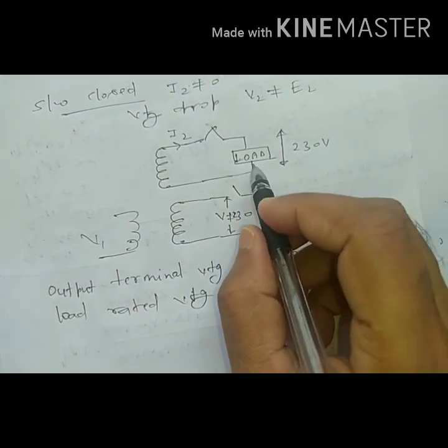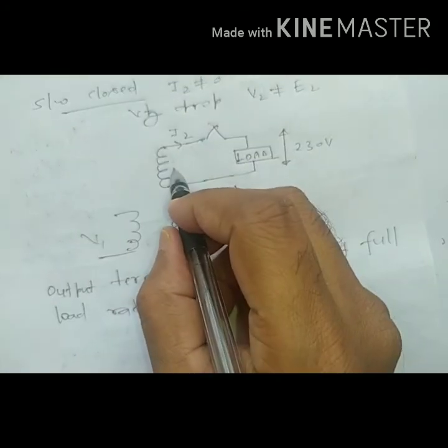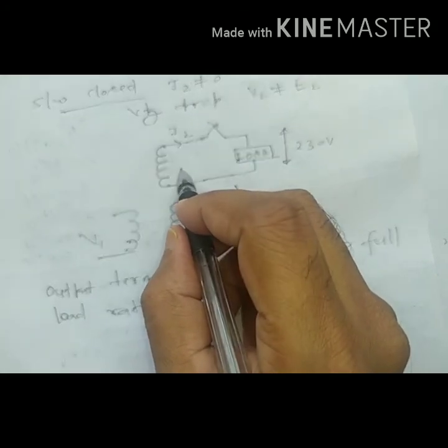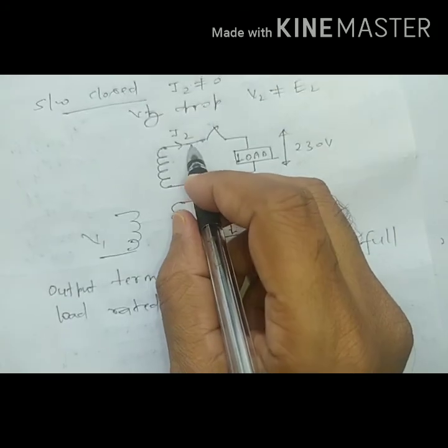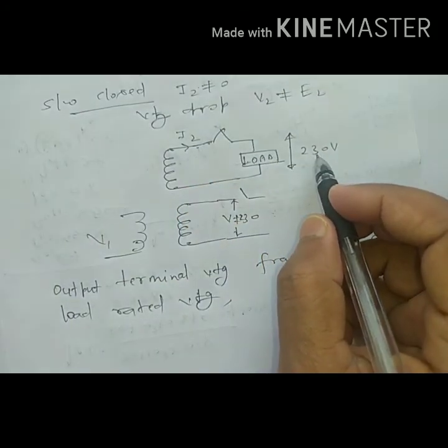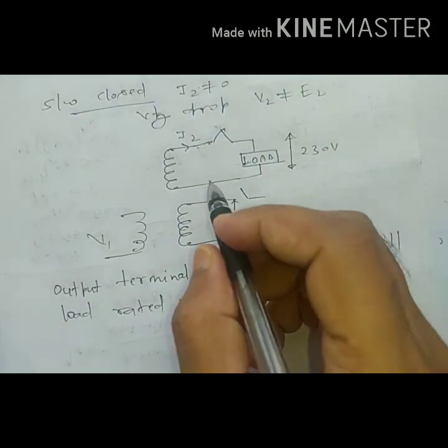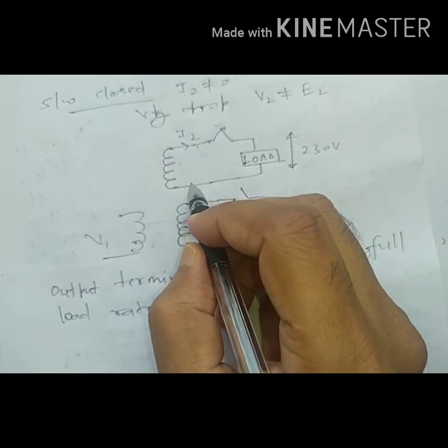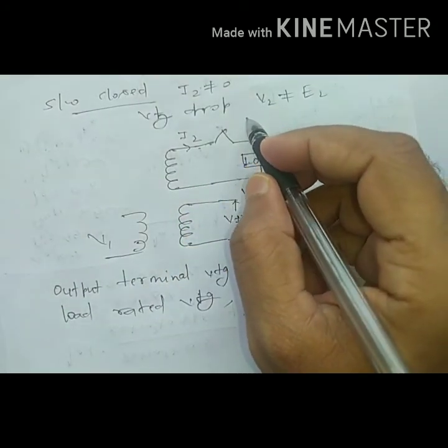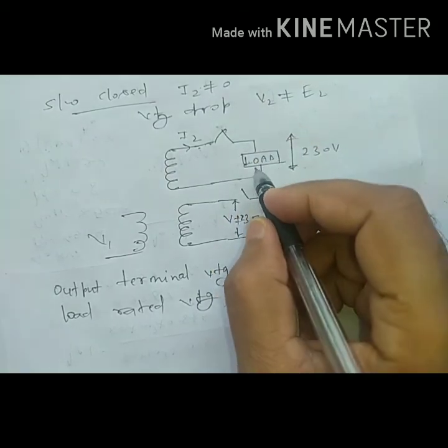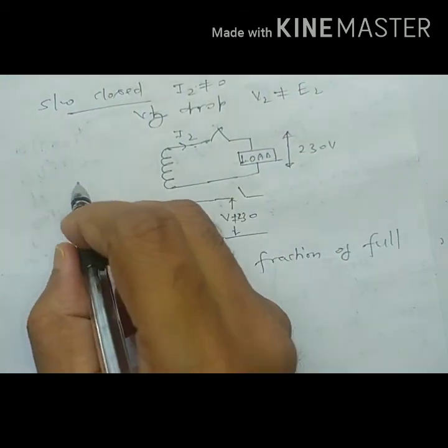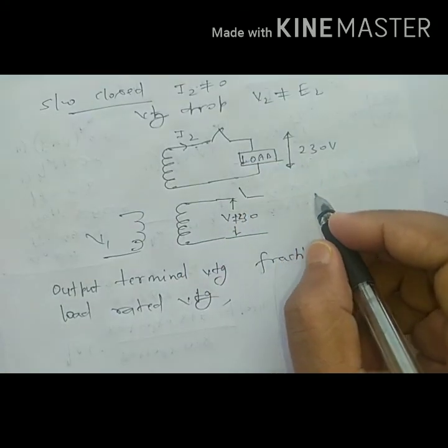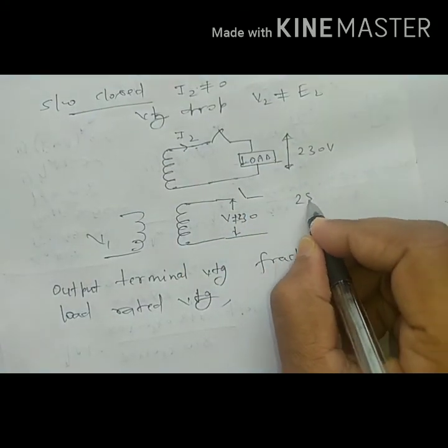So that means if it is 230 volts, here some voltage is there which is more than 230, because that voltage is providing the drop, and after that the available voltage is 230. Therefore that voltage can be measured only when I am removing the load. So if the load is removed, keeping input constant, the voltage available will be more than 230, say 250 volt.